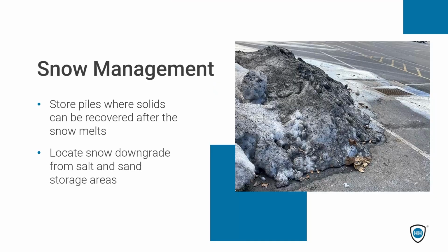And snow management. This is something seasonal, probably more for northern folks than for people in the south. But where do we put our snow piles? How do we manage those? Are they in an area that will allow us to capture all the sediment? So here you can see this pile is kind of dirty, a lot of sediment in that. If we're just taking that snow and putting it into an area where there's soil, all of that sediment is going to get into the soil, and that's going to inhibit the soil from allowing water to infiltrate eventually.